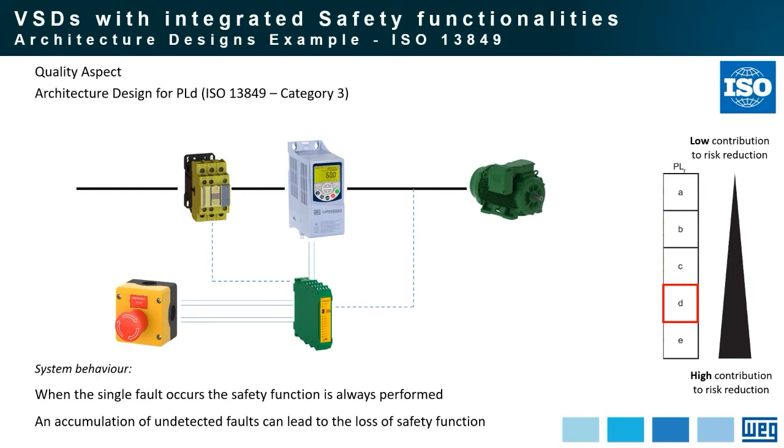And so in this system, when we have, for example, a problem with the cables between the emergency push button and the safety relay, the safety relay will set the warning. But again, a second cable, a second connection between the emergency push button and the safety relay will make sure that the safety signal will be sent to the relay to stop the machine. So that is the meaning of redundant cables here between the emergency push button and the safety relay.